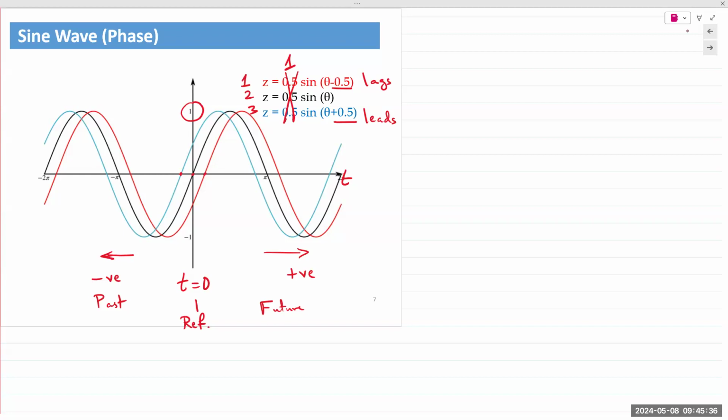Think of it in these terms. If these were mountains of dirt and you flatten them out completely, what would be the value of that waveform, or the equivalent DC value of that waveform? So even though right now we can say this is plus and minus, if you add them together it becomes 0, that's not fully the case. If they were all positive peaks, let's say you flip the negative peak, and you had a waveform like this, and you flattened it out, what is the value of that waveform? Somewhere over here, approximately, right?